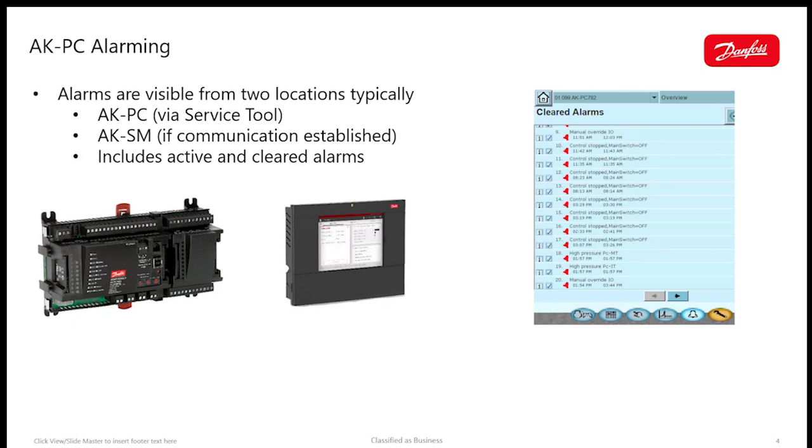And then the second area is through the system manager itself. We know in most installations that the pack controller will be tied back to a system manager for communication. The alarms that are generating in the pack controller are transmitted back to the system manager if configured properly, so that those alarms can then be transmitted out to something like a monitoring service provider or end user, so that they can be notified of those alarms if they need to dispatch a technician or just remotely connect to the store and do a little investigation. The second area that you'll see the alarms displayed is through that system manager.